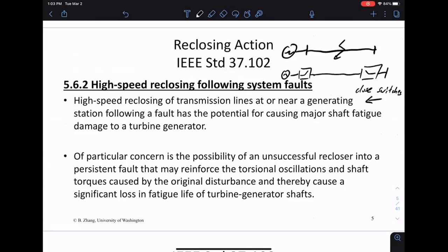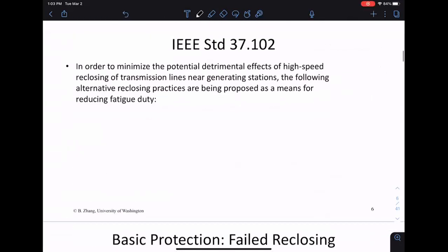All right, so if you look at this, the actual reclose action goes something like this, right? If you want to minimize the closing speed, then the reclosing action is very deliberate. It's not that fast. You have to wait a little bit. So we basically have sequential closing. A little bit on how the faults are cleared: we have sequential closing. We'll close from the remote end of a line.